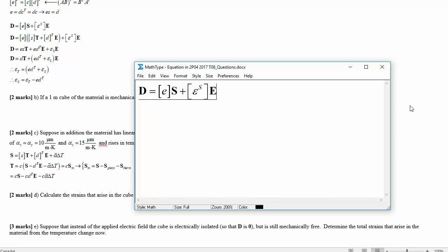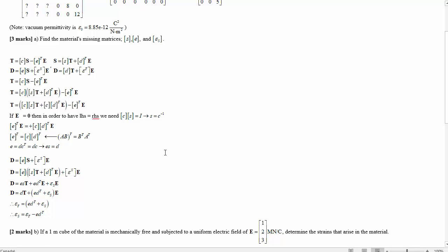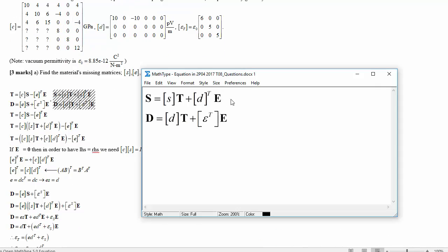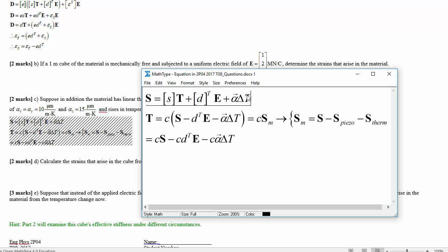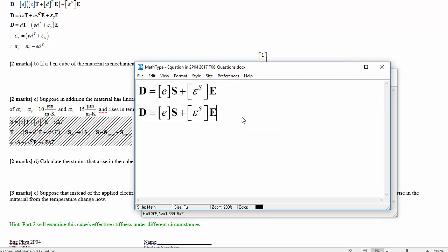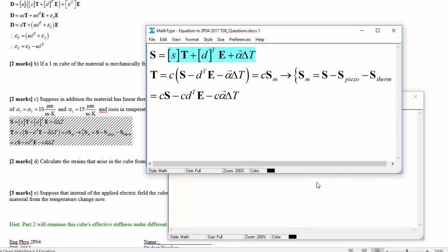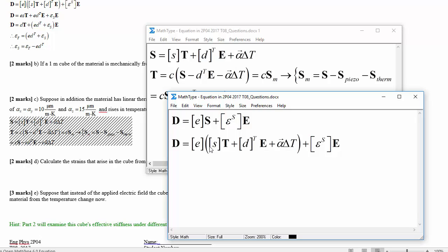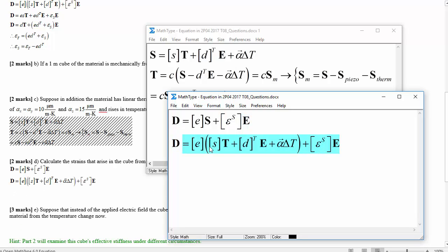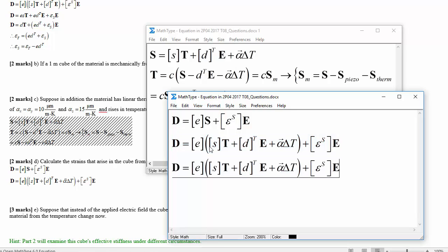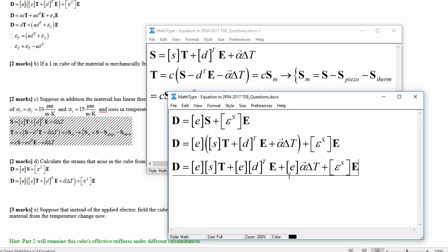And if you like, you can substitute in what you have for strain in the event of a temperature change. So if you want to add in the temperature change like we did in the previous setup here to this other form of the equation, then you can figure out a modified stress form of this equation, which is a bit convenient to do if you wanted to analyze analytically how things are working out and get a feel for it.